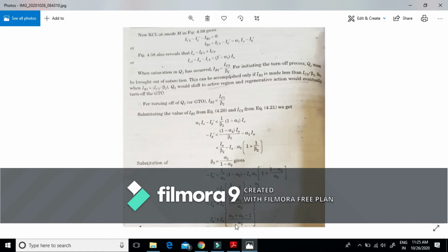This low value of current gain alpha 1 of transistor T1 can be achieved by diffusing gold or other heavy metal in the N base of transistor T1. That is already explained, that is by introducing short circuiting N positive fingers in the anode P positive outer layer. We have two techniques to obtain a low value of current gain alpha 1 of transistor T1. One is the gold doped GTO, and the other is the anode shorted GTO, or we can use a combination of both.